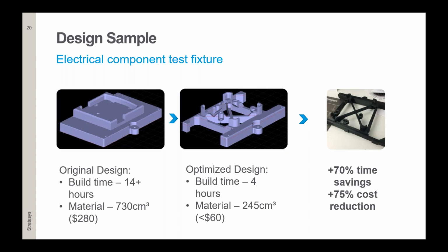Exactly. Thank you for this comment. So if you have some fixtures or jigs which should only be fixated by a certain geometry or at certain places, and you don't need that part to be performing or have a mechanical strength that high, you could reduce. So exactly, Stefan, it depends on application. If you see the opportunity to reduce the material and the weight, you might do that.